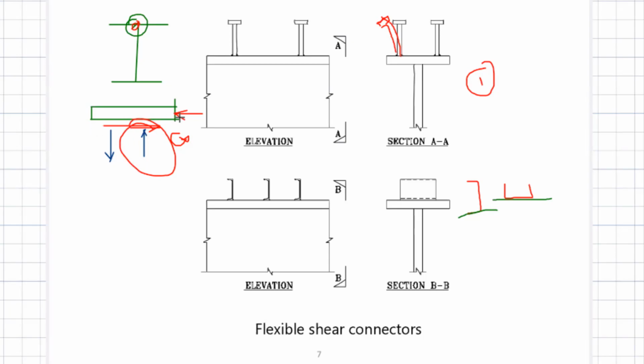So at the interface, my shear stud will be sheared, right? Basically because of the shear. But because of the equilibrium moment component, there will be an upward force also coming on the top of the connectors. So if you take a connector, there will be a force that shears it because of the interface, the double action, and there will be an uplift force, right, because of the moment equilibrium coming.